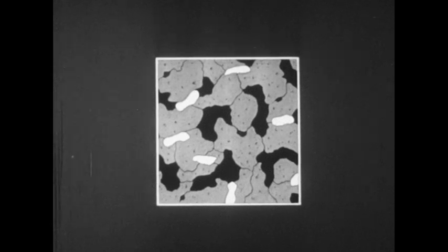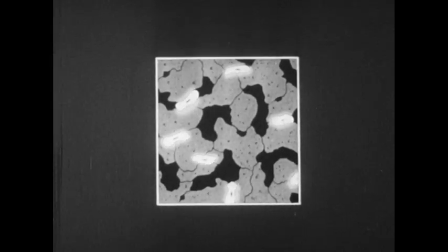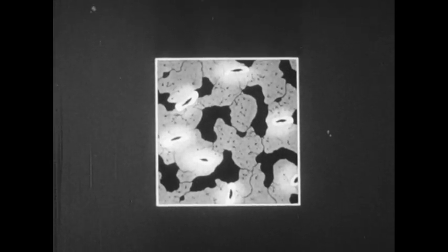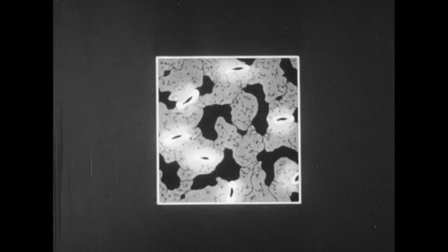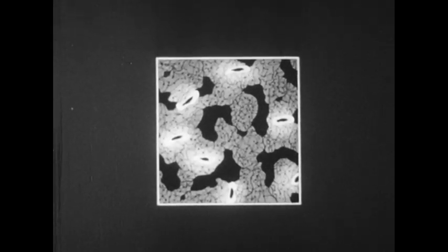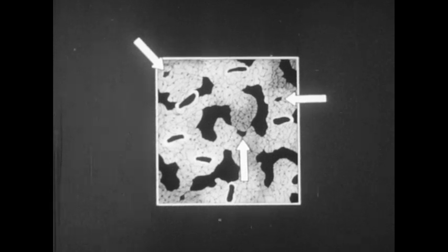Early in the sintering process, even before the briquette leaves the preheat chamber, the tin begins to melt and diffuses into the copper, leaving additional voids. Simultaneously, the stearic acid vaporizes, forming a network of capillary tubes throughout the briquette, imparting a spongy character to the whole structure. As the sintering continues, the diffusion of tin and copper is completed, and the final porous bronze structure is formed. The graphite, distributed in the bronze matrix, has not changed appreciably during the sintering.